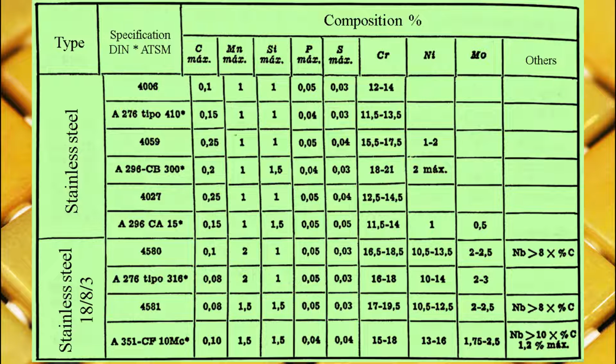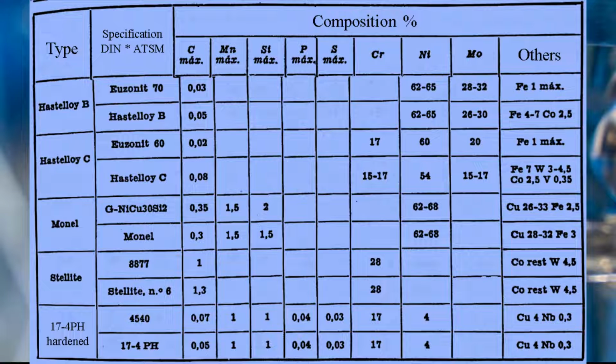The plug and seats are normally made of stainless steel because this material is highly resistant to corrosion and fluid erosion. Here we can see the standard and special materials used in plugs and seats. When fluid velocity is low, PVC, fluorocarbons, and other soft materials alone or reinforced with glass fibers or graphite can be used. Ceramic plugs and seats may be used on some valves.